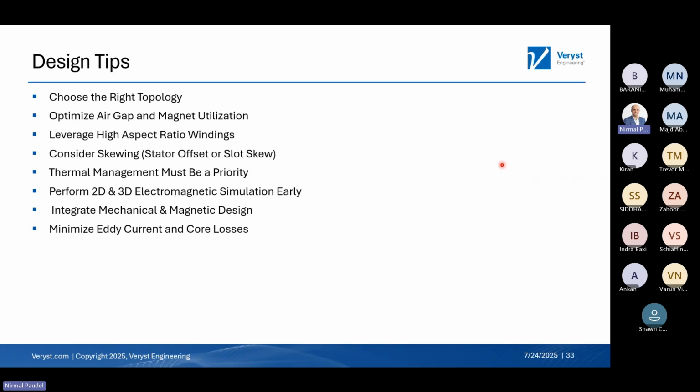Thermal management must be a priority. Again, that is a very different topic, but it's something you have to be mindful of even during the EM design. The design can be enhanced from the concept through prototyping using FEA tools, starting with 2D or 3D. You can always integrate that into the mechanical design as well, to calculate the forces on it. If there are any structural issues, you can mitigate them early on.